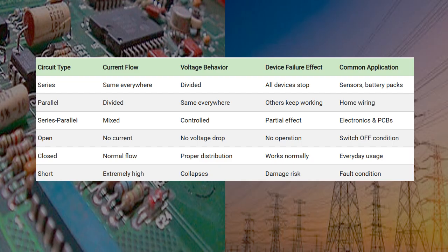In a short circuit, the current is extremely high. So that's one of the reasons why, in any power or electrical system they design, they have to test what happens if there is a short circuit, because the amount of high current that will flow through the circuit has to be sustained by the size of the conductor they use.